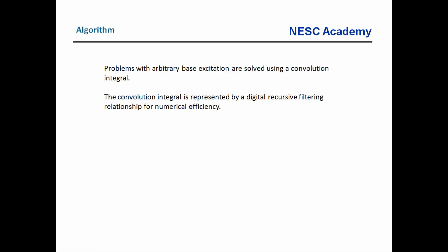Now, we've talked about the process in previous units of going through, setting up a free body diagram, using Newton's laws, and deriving a governing differential equation of motion. And if our base excitation function is something well behaved, like a sine input or a half sine input, then we can use Laplace transforms to readily solve that problem and get an exact answer.